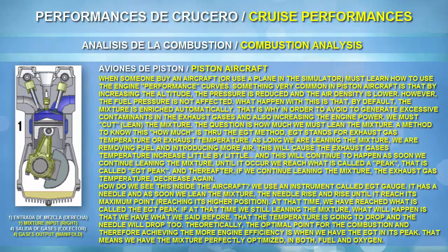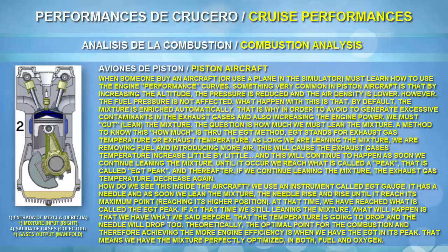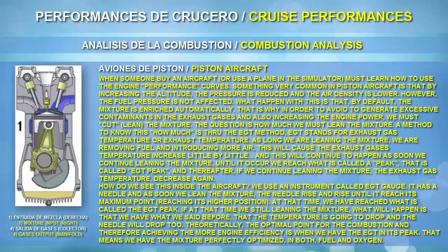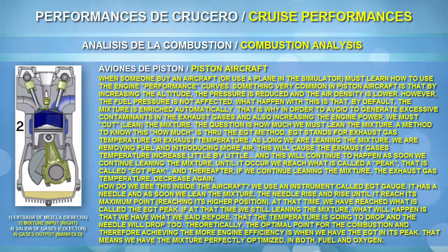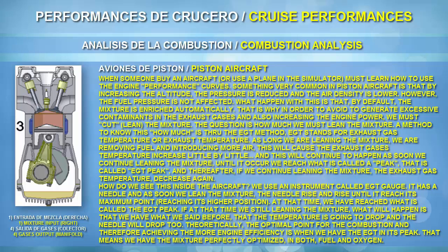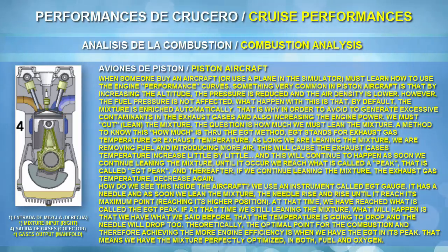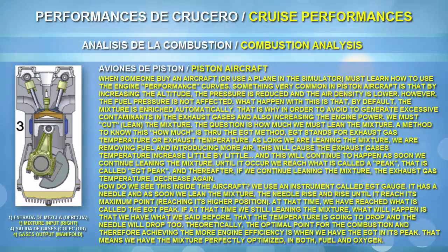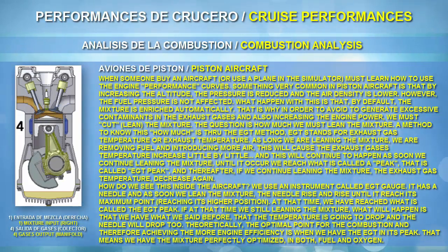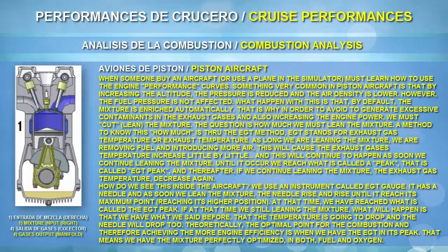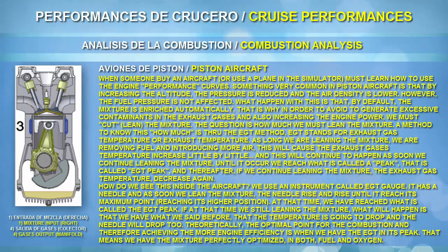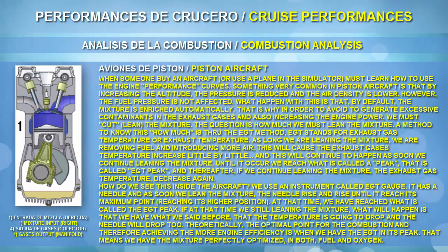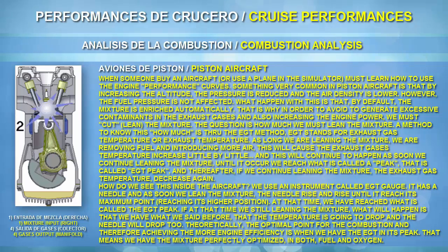But what you need to understand, to summarize this and make this easy, is that when you're ascending, we need to lean the mixture. We need to put more air to make the engine burn better the chicken inside the oven, okay? To make the engine burn the fuel inside better, we need to put a greater quantity of air inside the engine. That will make us fly in an ecological way, also because we won't produce a lot of contaminant waste,